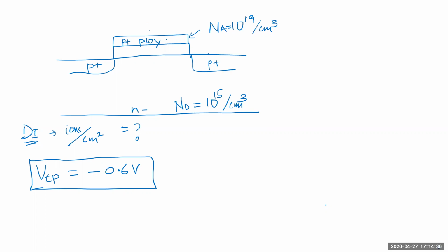For example, right now, if you are in that intuitive engineering mind, you'd say, I know the phi MS, because the Fermi potentials are reversed in that case, it'll be negative. And since ND and NA are the same, opposite signs but same value, the ln of NA over NI should be the same, and so on and so forth. I'm just giving you some vague guidelines. That's how you should try solving problems. You already know some basics, so use that intuitively.